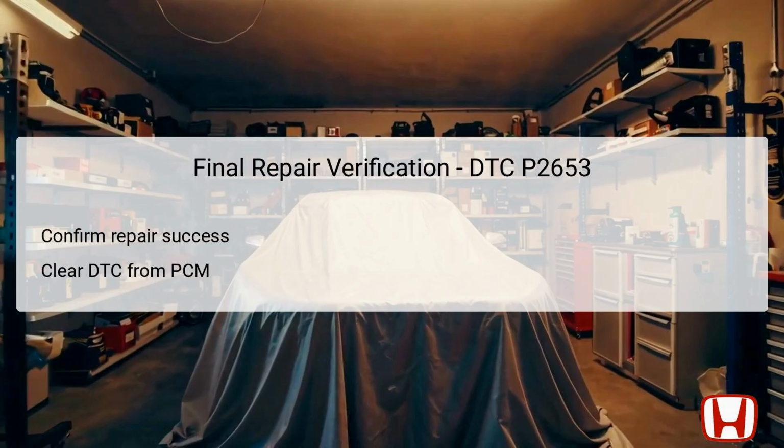Once repairs have been completed, it is essential to conduct a final verification process for the DTC P2653. This involves confirming that all necessary components have been repaired or replaced and ensuring that their functionality meets the OEM specifications. After making the repairs, clear the DTC from the PCM using a diagnostic scan tool, and then retest the system. Restart the engine and monitor the performance of the rocker arm oil control solenoid, as well as other related systems, to verify that they are operating correctly.